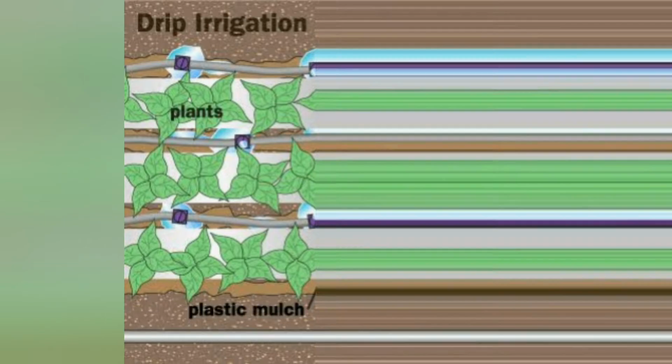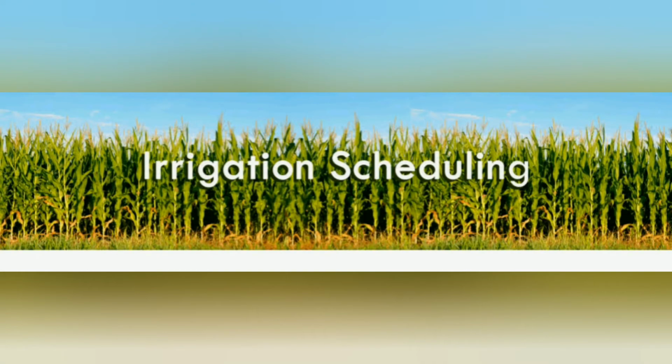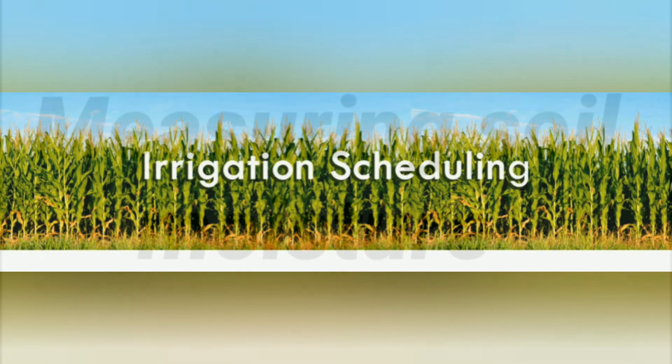And now, what is irrigation scheduling? Whichever type of irrigation system is used, it is important to use some method of irrigation scheduling to avoid drought stress and provide water when it is most needed. There are two basic methods of irrigation scheduling. The first type is measuring soil moisture. In this, a sensor measures the quantity of water contained in a material.